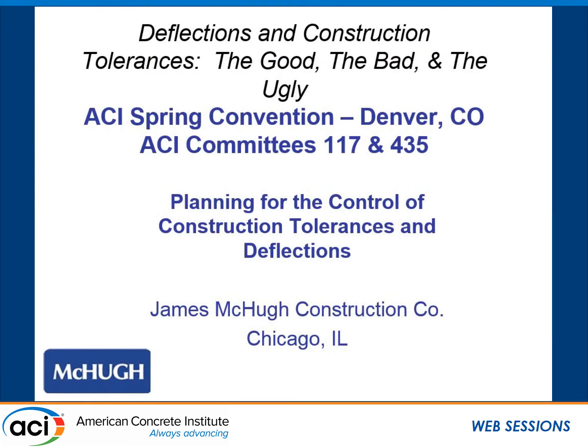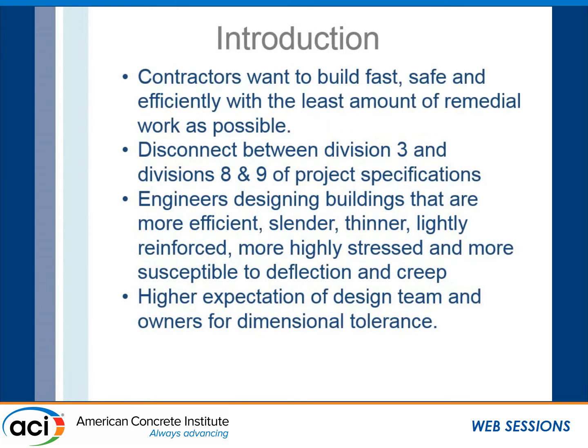The discussion today is about planning for the control of construction tolerances and deflections. As a quick introduction, contractors want to build fast, safe, and efficiently with the least amount of remedial work as possible. That goes without saying. But unfortunately, what's stacked up against us is a disconnect between Division 3 and Divisions 8 and 9 of the project specifications. Division 3 being the concrete and 8 and 9 being various finishes.